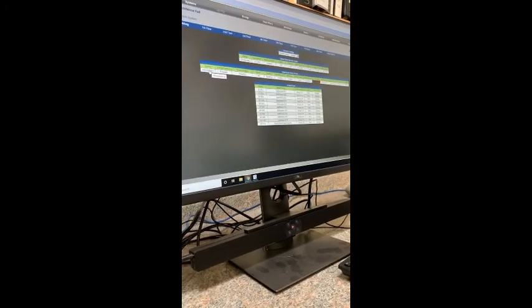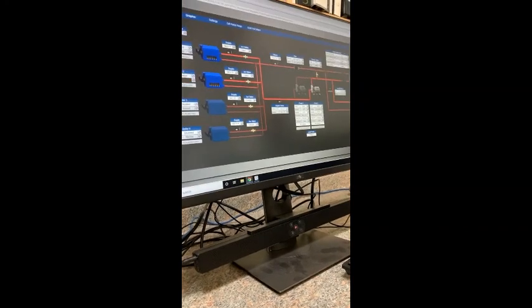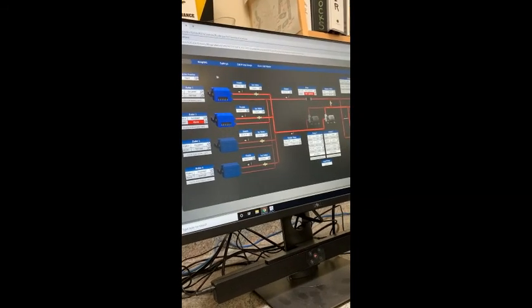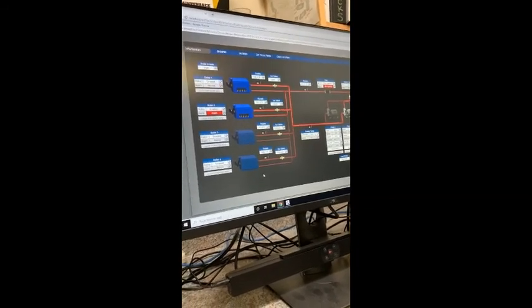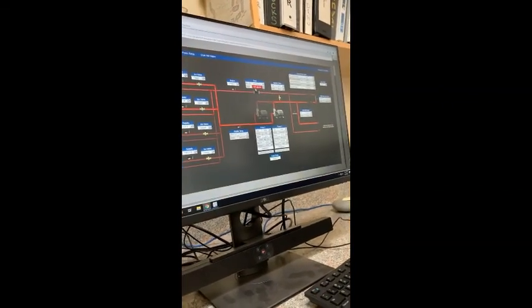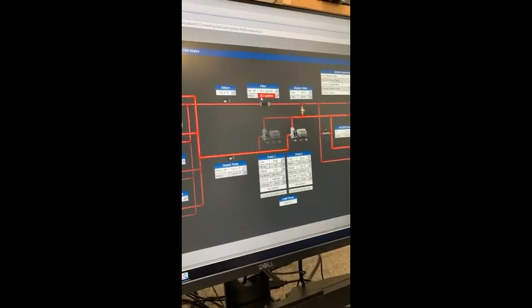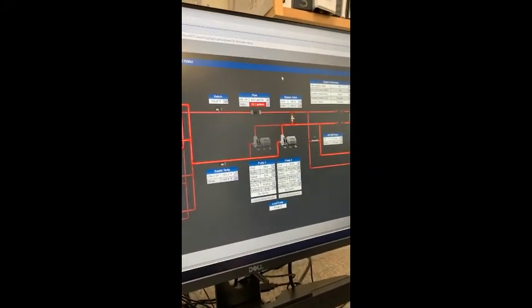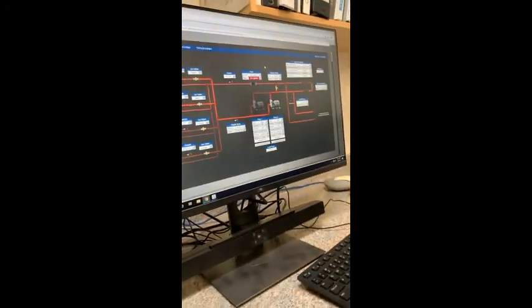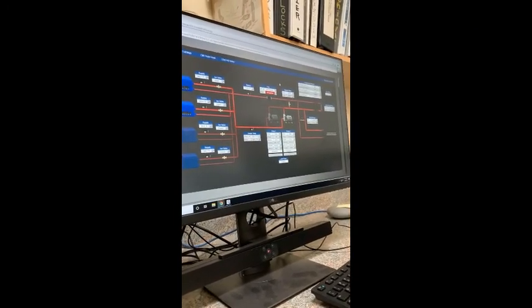The other main system that we have here is, nope, I clicked too fast. Yeah, it's the heating hot water system. So we have 4 boilers. We can see right now we have a minimum flow alarm. So it's saying that we're not flowing enough minimum water, but we are trying to bypass to raise that flow up. Why we're not flowing enough water, I'm not sure. For the boiler specifically? Yeah.